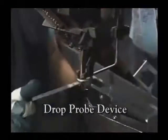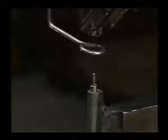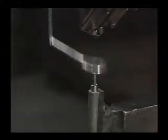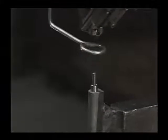A drop probe is a small metal device that drops to a predetermined spot an instant before the machine starts. If the drop probe falls freely, the machine begins its movement, but if it hits a worker's hand or other obstacle, the machine will not start.